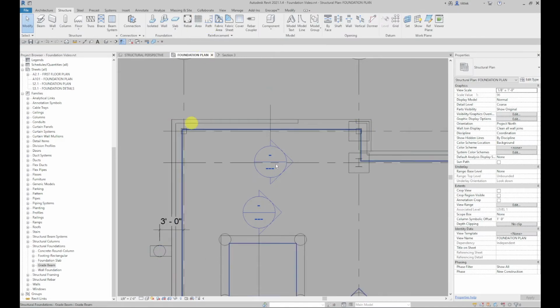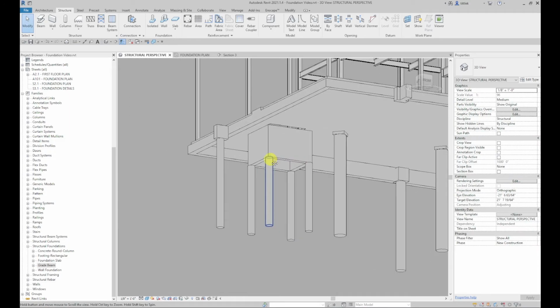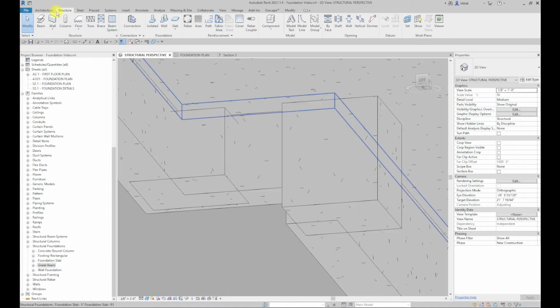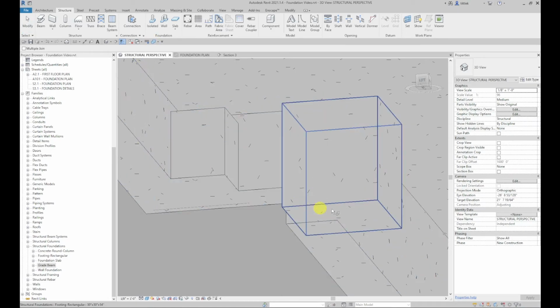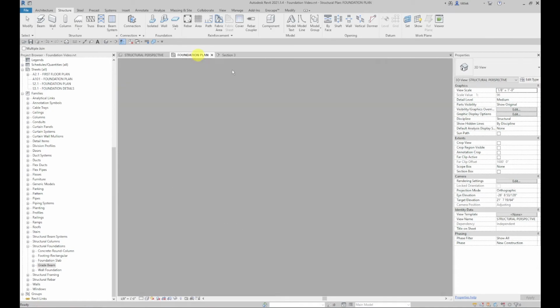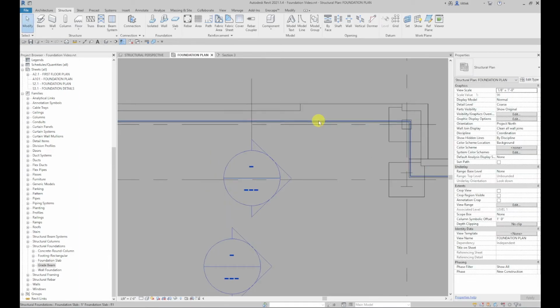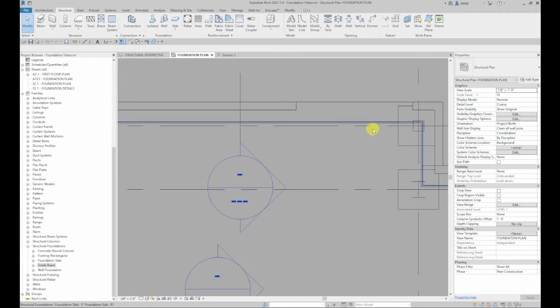So to make this look right, one thing I'm going to do is go in here, and I don't have the whole thing done, but you can go ahead and do the rest of those. But let's do the join of our footings to the grade beam, because again, these will be poured monolithically with the grade beam. So we want to show that. And if we go back to our foundation plan, now what we can do is we can address some of these lines that we see.